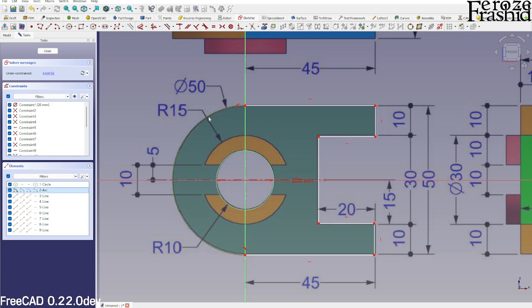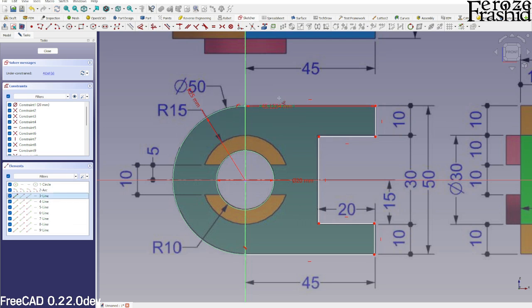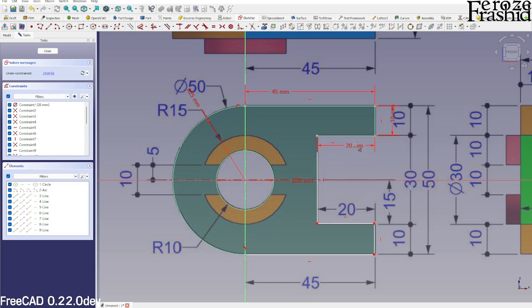All right, and this is diameter 25. I'm gonna go ahead and actually apply the rest of the dimensions in there real quick. And this is going to be 20. And then what I'm going to do, I'm going to make these two as if they're symmetric. So make them equal. And that constrains everything. Like I said, there is only point on line constraint, and here's the tangency constraint. These are two different ways to actually do the same thing.